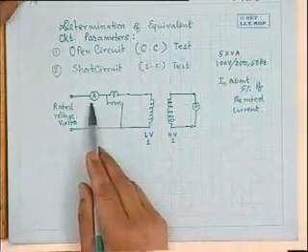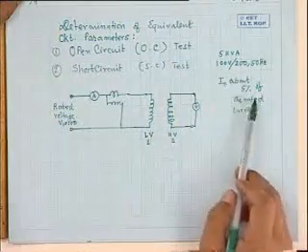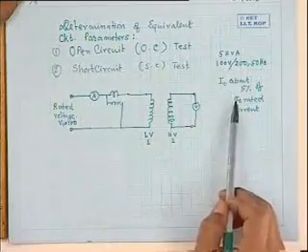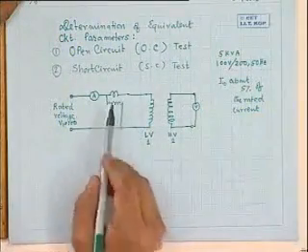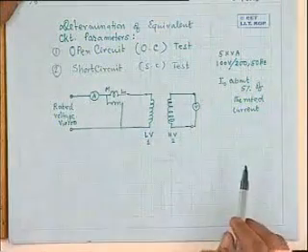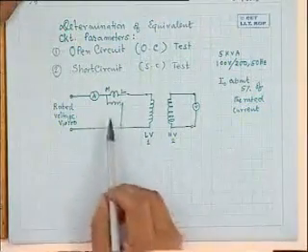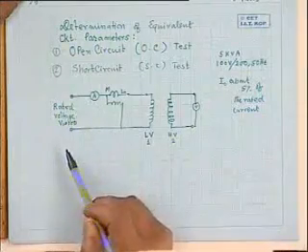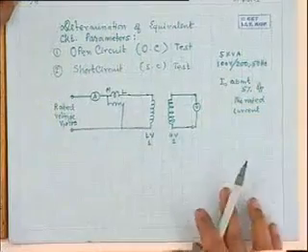Therefore, while selecting the ammeter range, we can easily calculate from the rated current, take 5% of that and select the ammeter range. This will also help us to select the current coil range of the wattmeter from this knowledge of current. Pressure coil rating should be related with the voltage you are going to apply. So you accordingly set up this one.